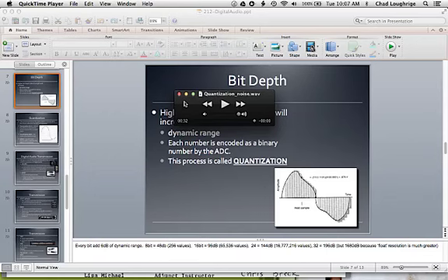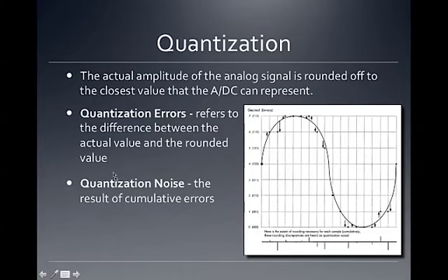At 16-bit, the quantization noise that we heard was really low, so low that we couldn't hear it. The quality sounded fine. At 8-bit, we heard that noise get a little bit louder because there's more rounding off. At 4-bit, we can hear it's really distorted. So hopefully that gives you an understanding of why bit depth is really important, and also gives us a higher level of dynamic range. Again, at 24-bit, we get 144 dB of dynamic range. It's 16 million velocity levels that we get to record.